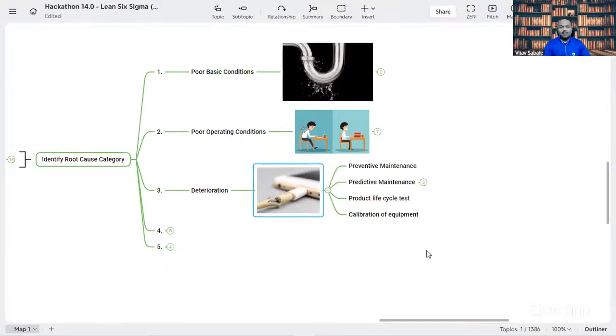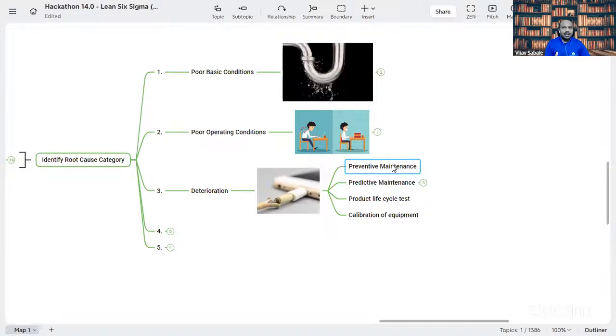So these are some of the things, I'm just giving you some examples, right? So you can have preventive maintenance. That means you already know the life or the duration after which you need to do some maintenance. Might be it is cleaning, or we need to check the things, fix them, remove them, or replace them. A lot of things we can do based on the machine manual, machine specification, and our learning experiences as well. That's why it is important to involve subject matter expertise as well.